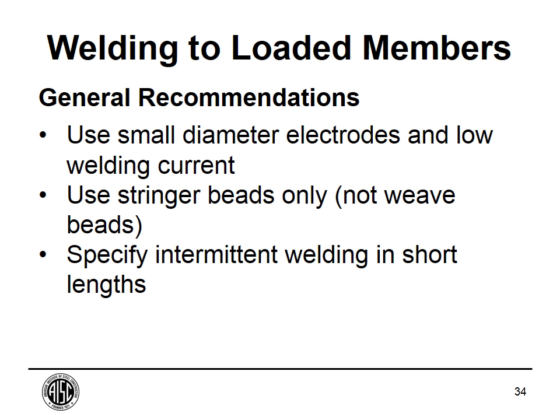So stringer beads. Usually, if you look at a WPS, it's going to say stringer or weave beads. It's going to have an option there. So you may want to just go with stringer beads, which is exactly what it sounds like. It's just a straight line. It's what we think of when we think of welding. It's just welding along a straight line. Now, weave beads, on the other hand, are just like it says, it weaves and it stays in that one area for longer, which adds more heat input in that area. So just kind of use judgment on things like this. And then, of course, we've already talked about the stitch welding.